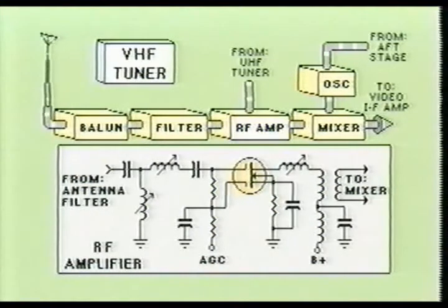Since the VHF frequency range extends from 30 MHz to 300 MHz in the TV tuner, shielding becomes necessary, wire length between the components must be shorter, component leads must be shorter, intercapacitance in the active components starts to become more of a problem, connecting wires are made larger to obtain a higher Q for the circuit, and LC circuits are replaced with pieces of bent wire or short pieces of coaxial cable. In general, the RF amplifier circuit becomes much more difficult to work with.